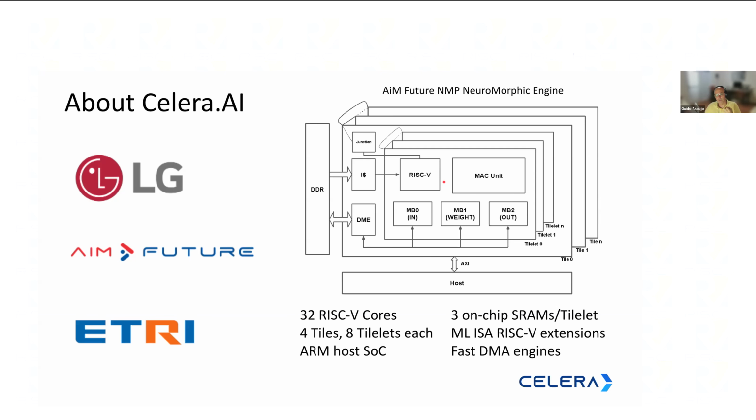So you extend the RISC-V and you throw a 3D convolution instruction there, a ReLU instruction there, etc., which are all based on a MAC unit. And these MAC units read 3 scratchpads. It's not a cache-based design, it's a buffer-based design.